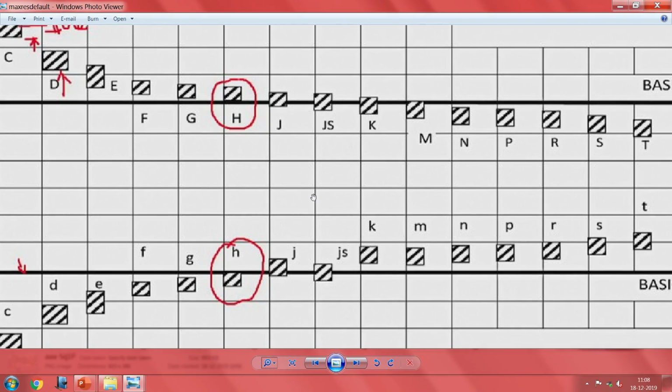In contrast, when you are having hole based one sided simple tolerances, H and small h are used. In the case of small h, you have seen this, always the shaft is smaller than the nominal dimension, and in the case of the hole it will always be bigger than the nominal dimension. And then the earlier slide showed you the range of fits and so on.